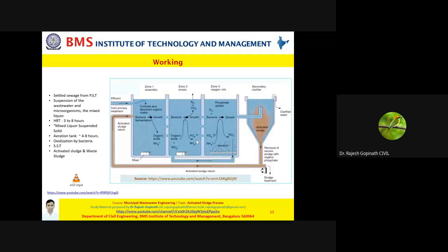All right, the second assumption is that the breakdown of your organic matter by this process is happening only in the aeration tank, not in your primary clarifier or your secondary clarifier. And how do we go primarily with respect to the design aspects? For that, we need to consider the volume of the aeration tank itself. So primarily we are looking at the aeration tank as the main reactor wherein the ASP process is happening.